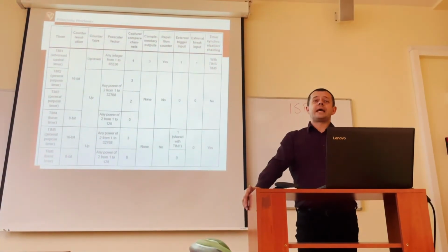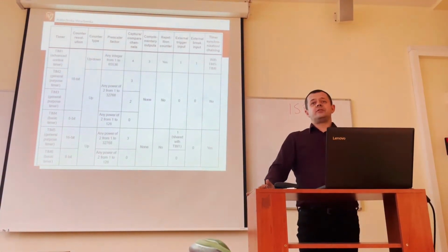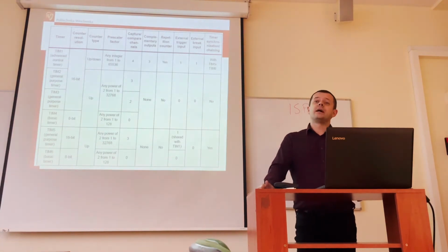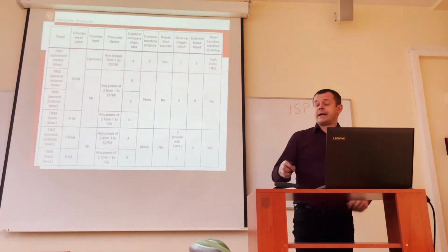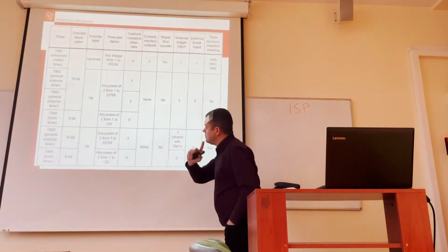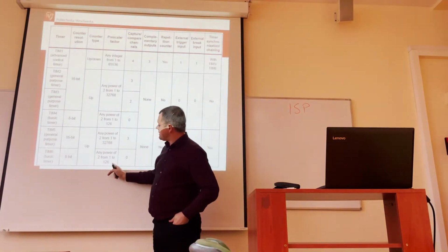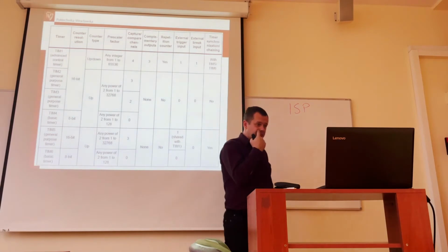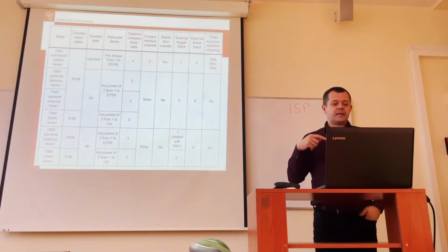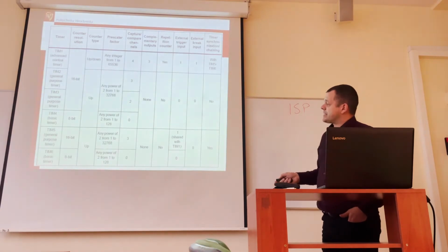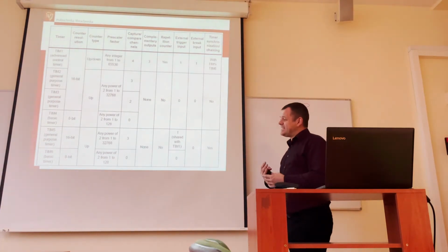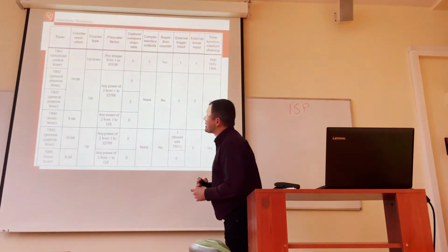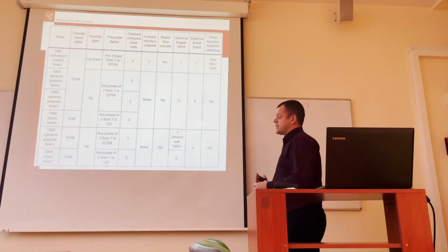They are very, very short from a practical point of view, and if you start using them, you must really be very careful about overflowing, about them counting beyond the range. Although sometimes the 8-bit timers have a bit of sense if we use a pre-scaling factor. Today it's quite common that the timers have a pre-scaler of the main clock, artificially extending the resolution or the range of operation of such a timer.